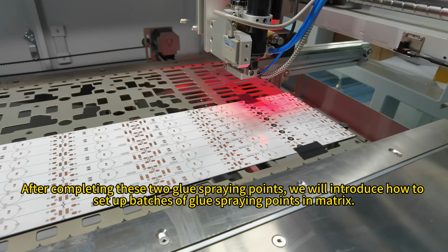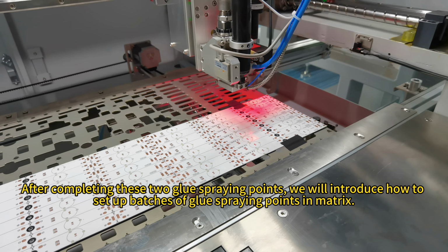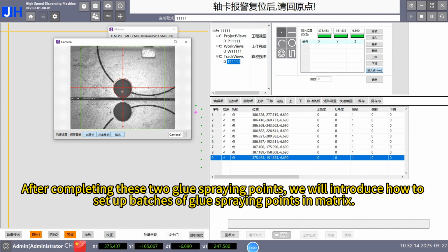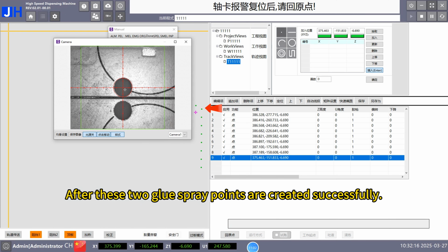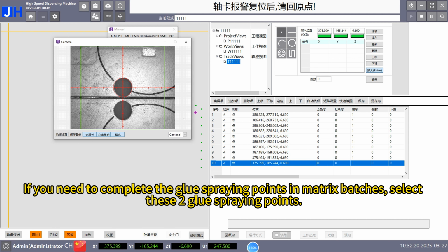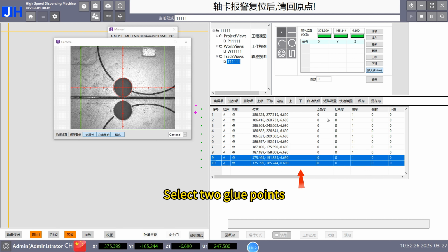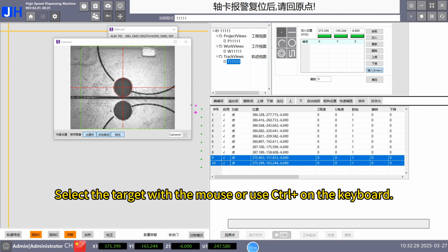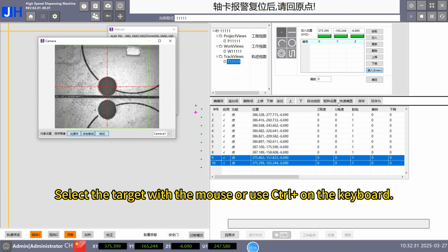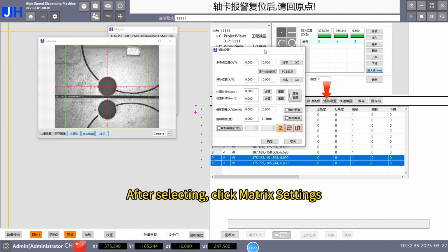After completing these two glue spraying points, we will introduce how to set up batches of glue spraying points in matrices. After these two glue spray points are created successfully, if you need to complete the glue spraying points in matrix batches, select these two glue spraying points. Select the target with the mouse or use Ctrl on the keyboard. After selecting, click Matrix Settings.